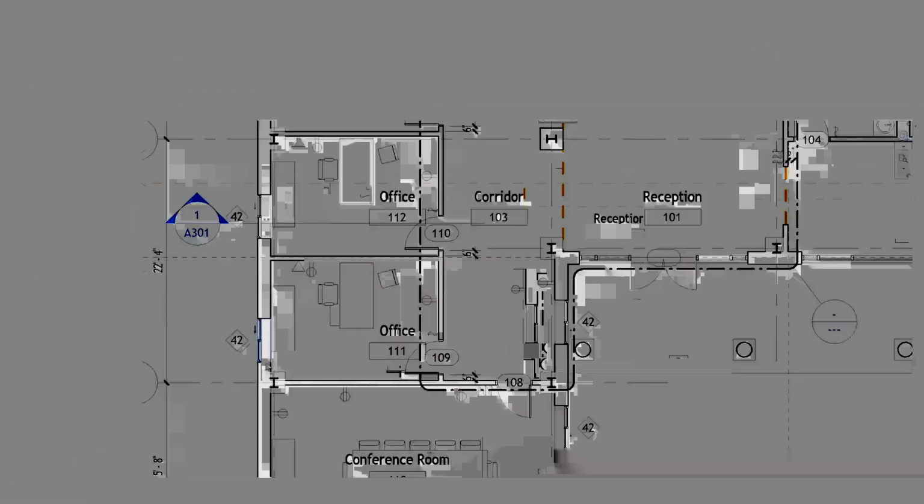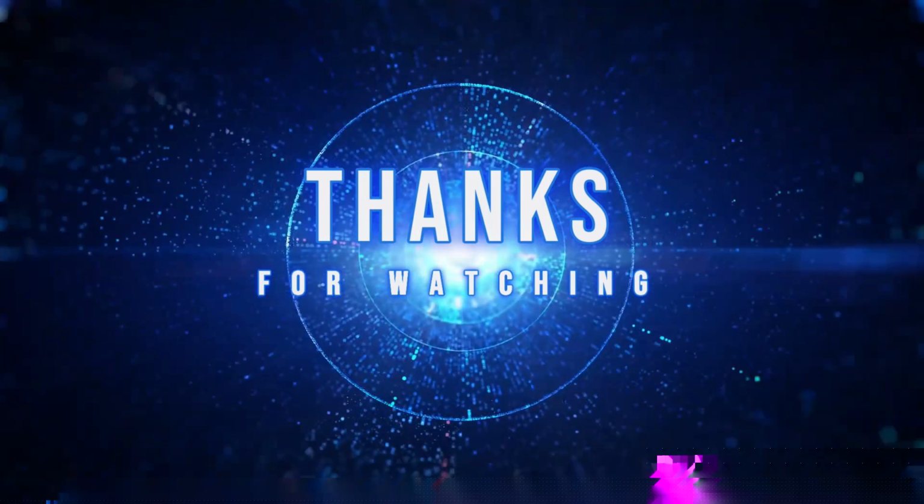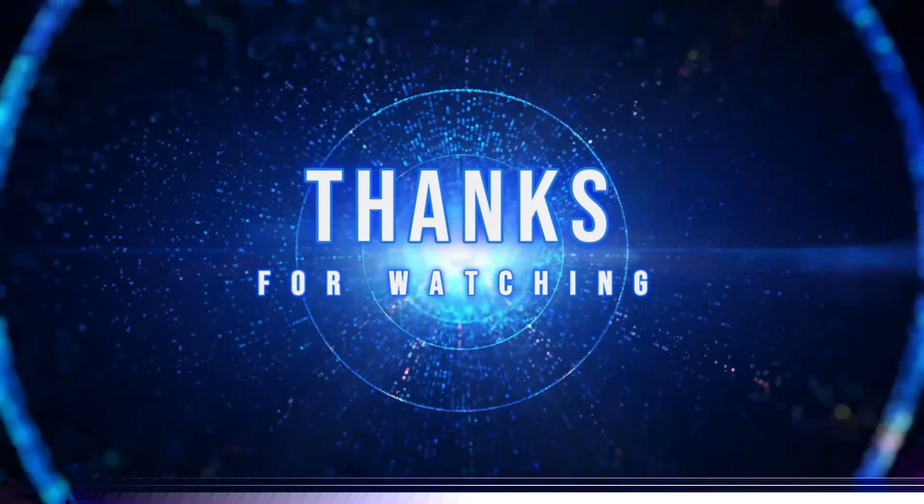If I grabbed hold of this reception desk here and moved it, notice that as I click through the other views, not only is it moved in each of those views, it's still selected. There's only one reception desk, and we're just simply seeing it in three different views and rendered in three different ways. So feel free to experiment further with visibility graphics here in this view. This is a very common and powerful command that once you start using Revit on a regular basis, you'll find you're using visibility graphics quite frequently as well.